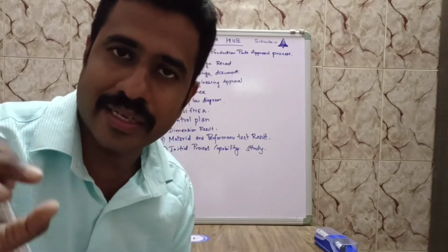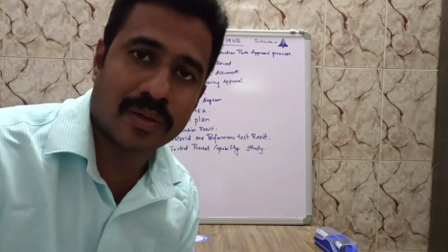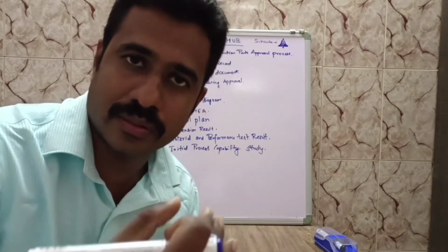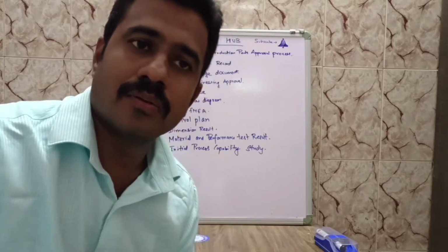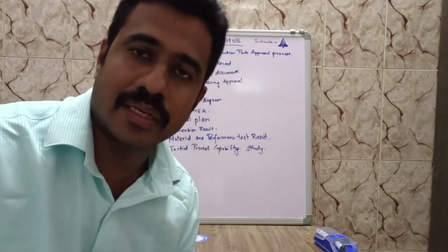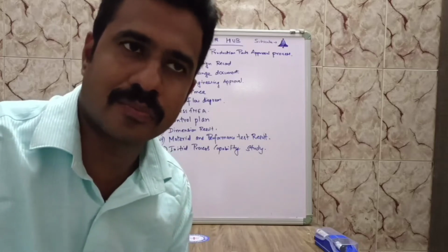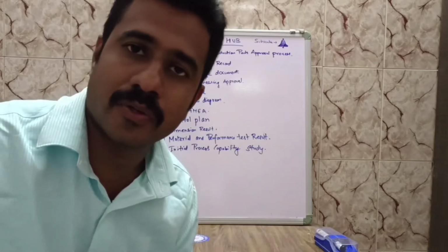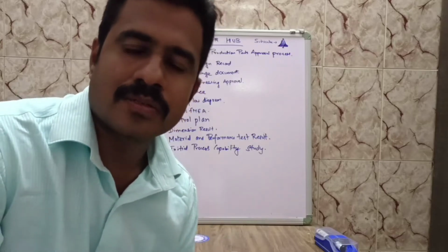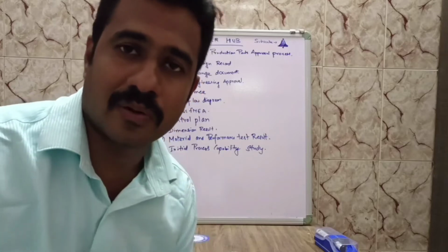So with 15 numbers, you have to check the readings of all the dimensions, what are the critical dimensions available in the product, as per the drawing. You take readings of those parts, and you plot a chart regarding that, the bell curve diagram. You need to compare those things. Okay, there's a CPK and CP value, and it should be above 1.67 and above 2. I'm going to give details in a separate video. Right now, just a simple explanation of what these terms and documents are.